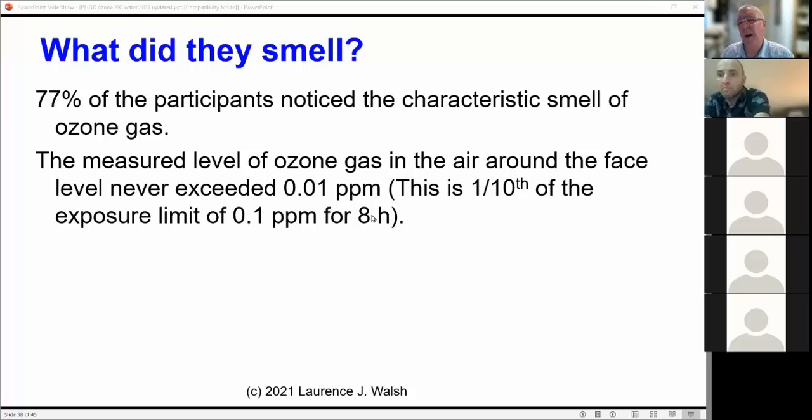You might be thinking, what on earth job would give you a high level of exposure to ozone? And the answer is if you're a welder or a boilermaker, because you spend a long time using a welder and you're often in an enclosed environment. And welding, of course, is throwing a very large electrical arc, so it does generate ozone.